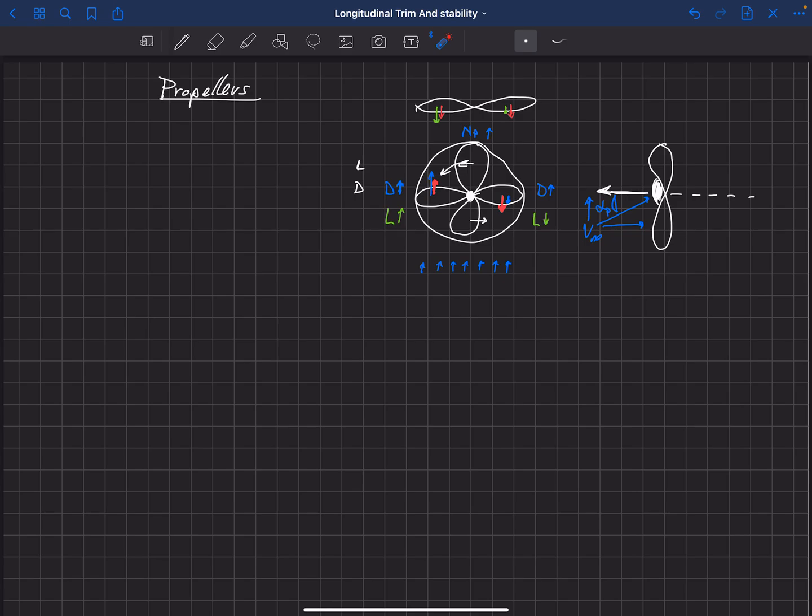So let's just look at this from a longitudinal stance, and we'll go back to our white here. So let's say that we have our center of gravity and a fuselage reference line that is aligned with our thrust vector, and this is where our propeller is, right here. And in general, we're going to say that this is L sub P, that's the distance after the CG to that propeller, and H sub P is the vertical offset of that propeller.